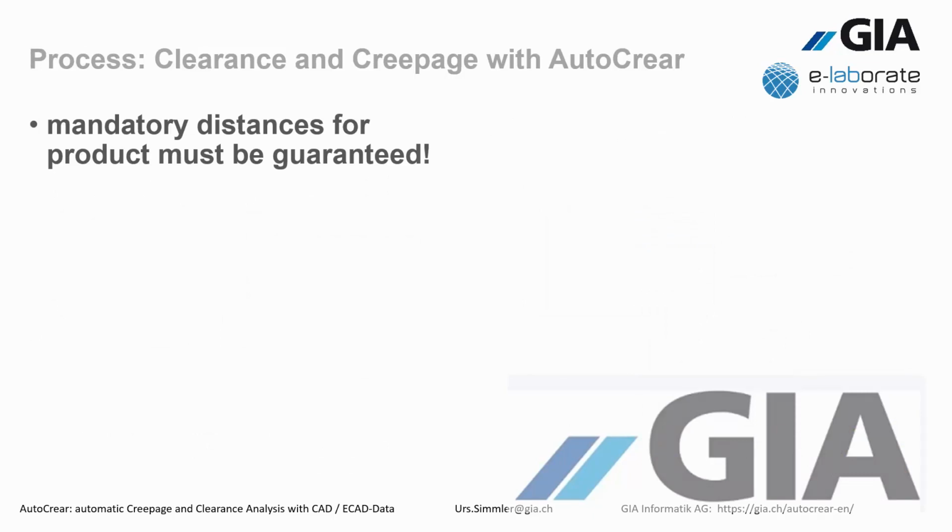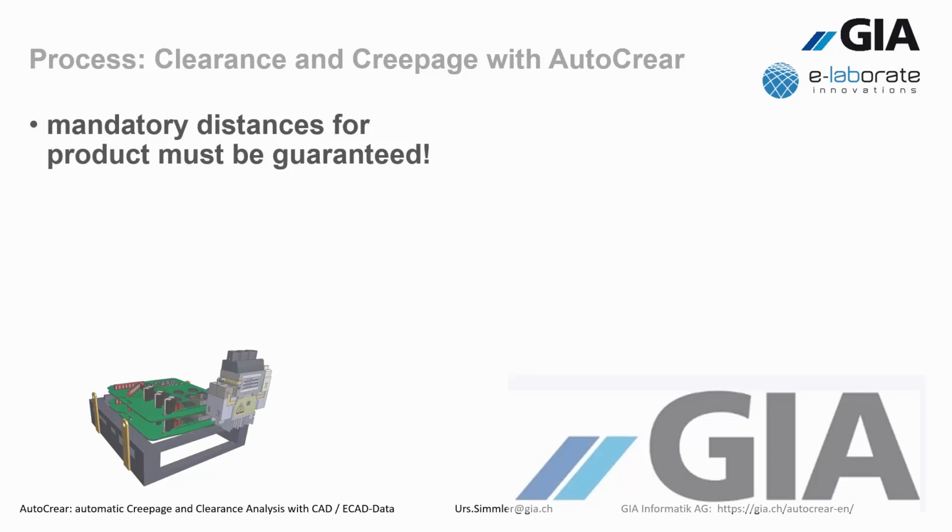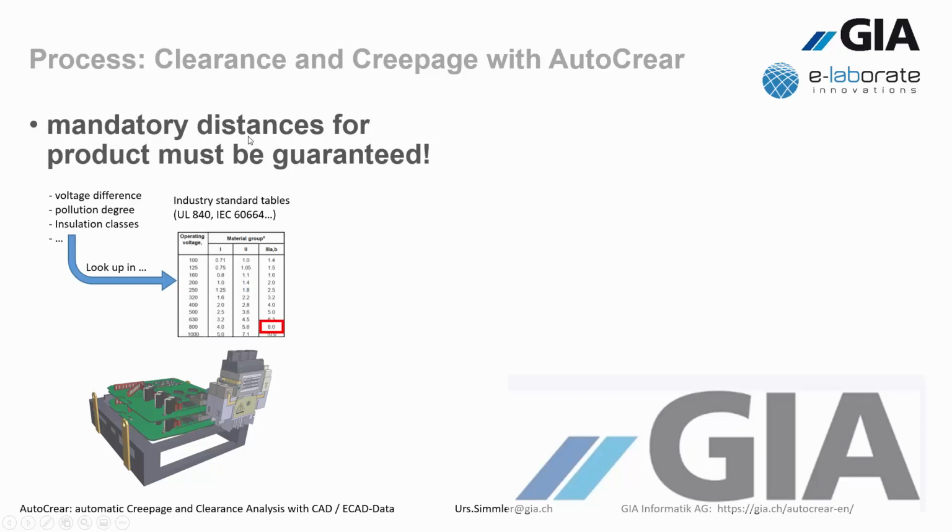I think it's mandatory that these distances are guaranteed for your products, and it depends on the voltage difference of the potentials of the networks, on the pollution degree, and on the insulation classes. With that information, you can go to tables, maybe from UL or from IEC, and find out, depending on the material and the voltage difference, what distance you need.